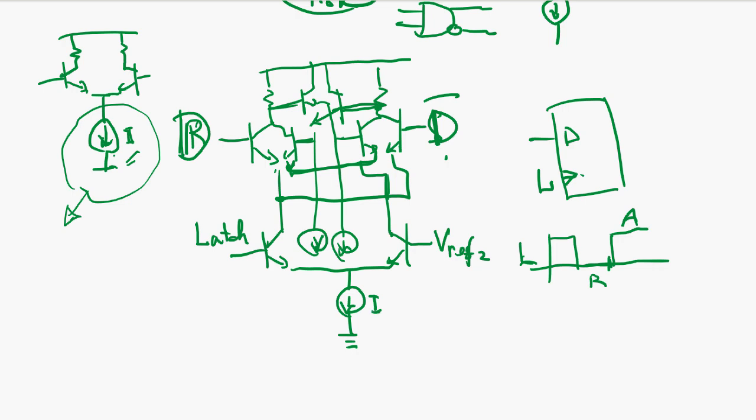So the logic switching gate, the switching speed is pretty much controlled by this current, how much power you push in, because the current is going to speed up charging and discharging parasitic capacitors around the transistors. So when current is large, then this resistor becomes small, because if current is 10 milliamp and a 600 millivolt swing, how much do you need? 60 ohm, right?